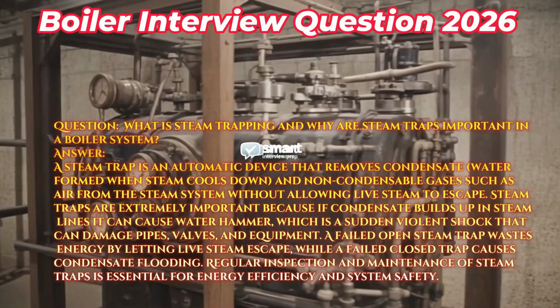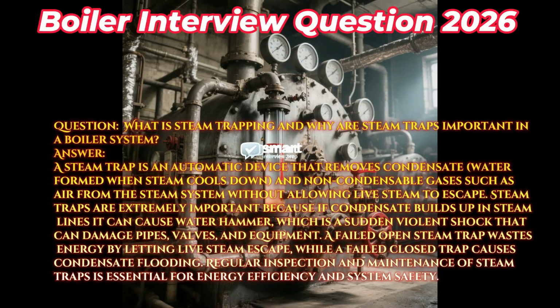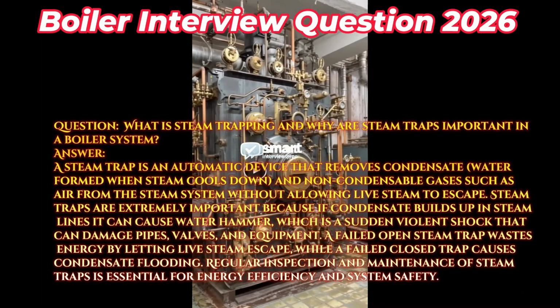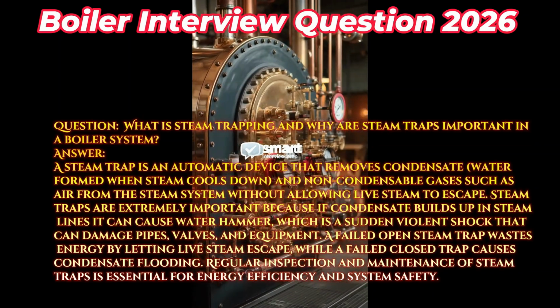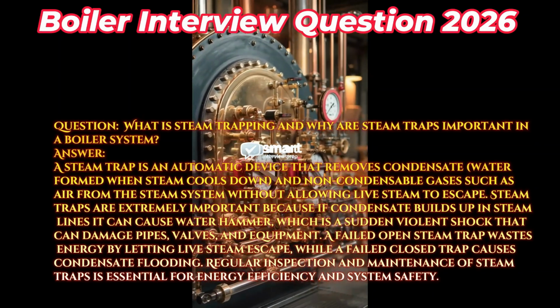A failed open steam trap wastes energy by letting live steam escape, while a failed closed trap causes condensate flooding. Regular inspection and maintenance of steam traps is essential for energy efficiency and system safety.